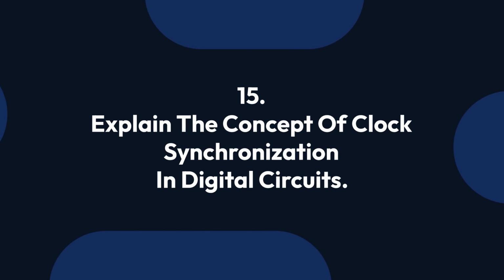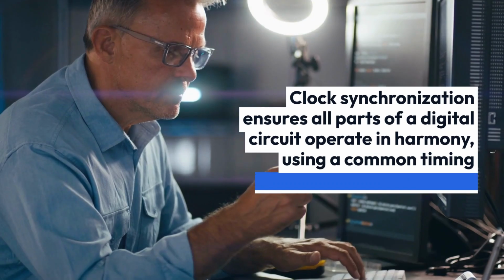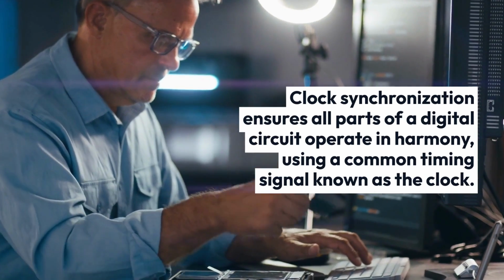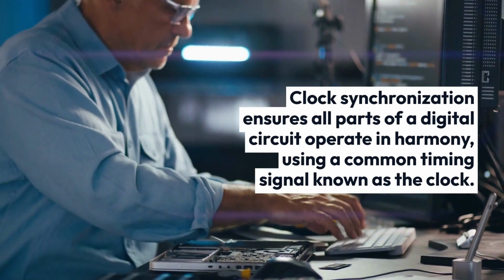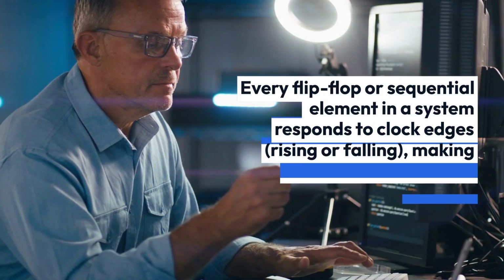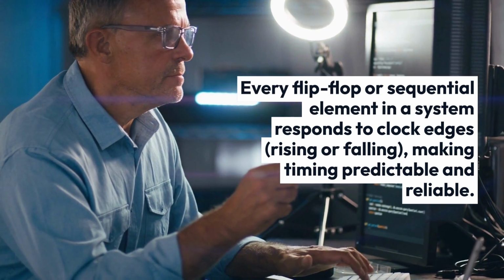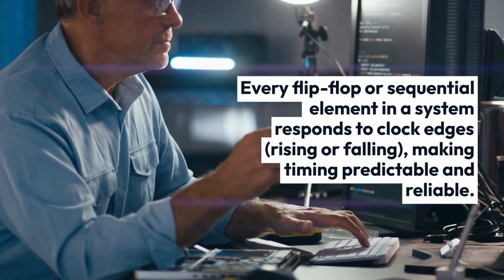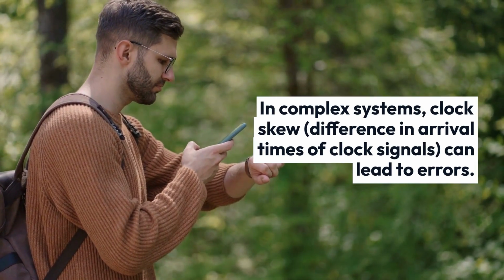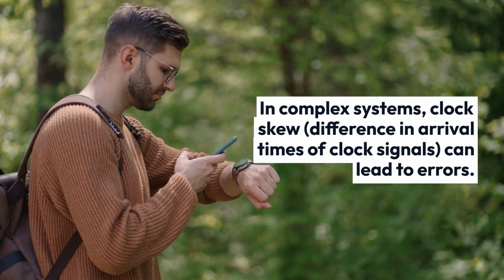15. Explain the concept of clock synchronization in digital circuits. Clock synchronization ensures all parts of a digital circuit operate in harmony, using a common timing signal known as the clock. Every flip-flop or sequential element in a system responds to clock edges, rising or falling, making timing predictable and reliable. In complex systems, clock skew, the difference in arrival times of clock signals, can lead to errors.